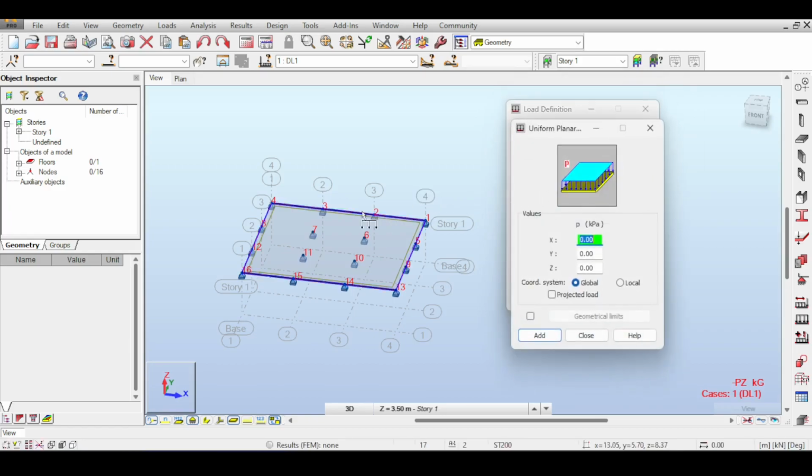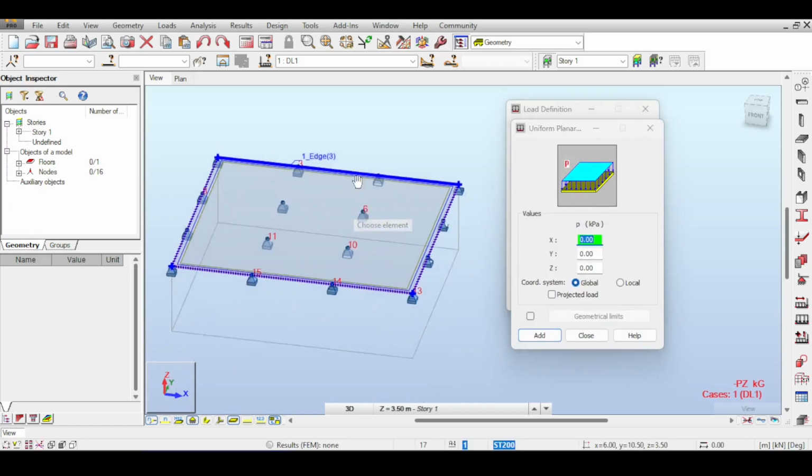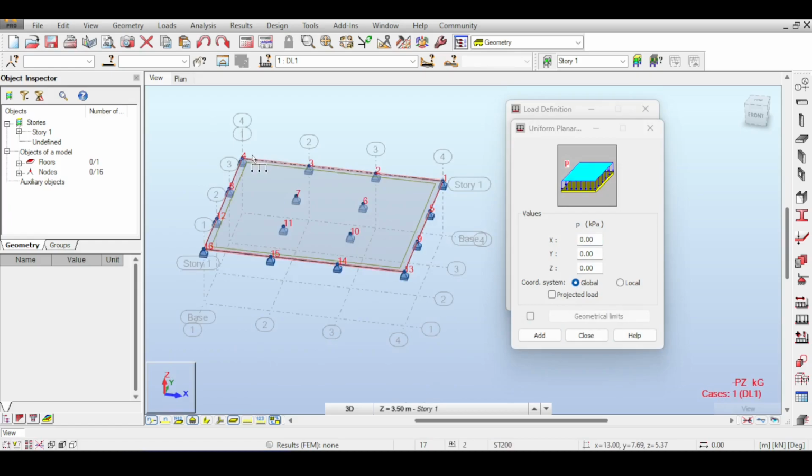Now we need, of course, the dead load calculation, which is something you'll learn in all your design courses. Let me just remind you very quickly. You have load partitions on the edges, wall partitions on the edges, wall partitions in the center, and you have covering material both below and above. This is something you learn in your elementary design courses in university.